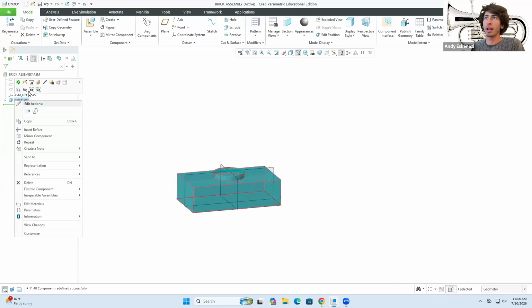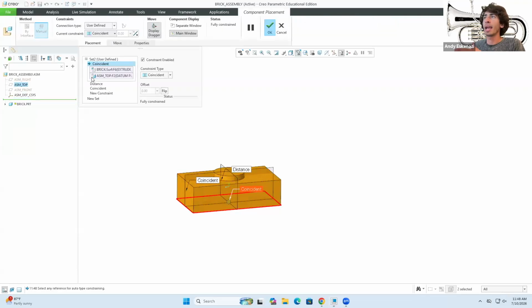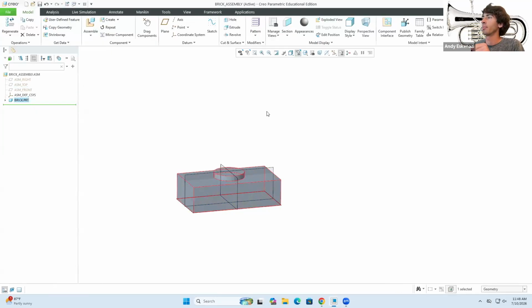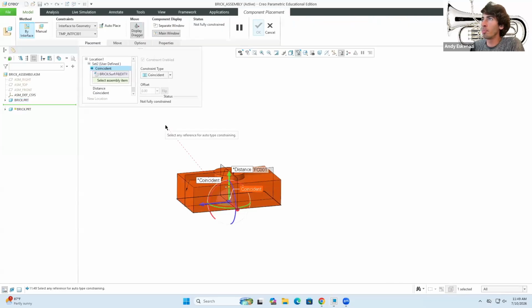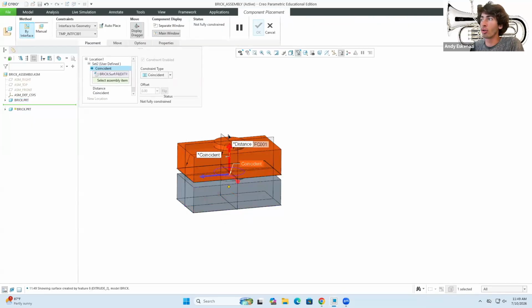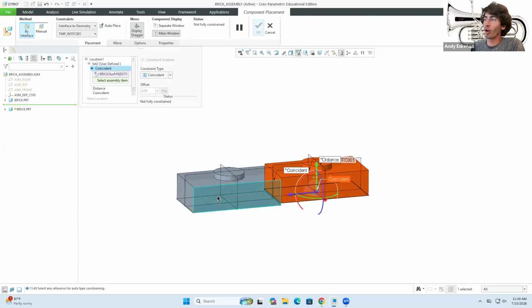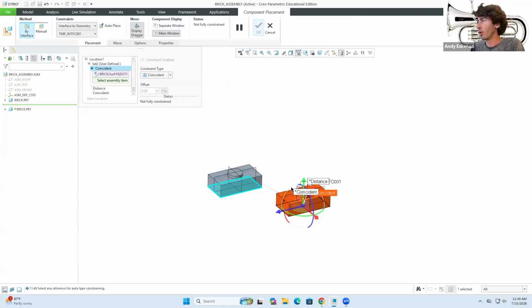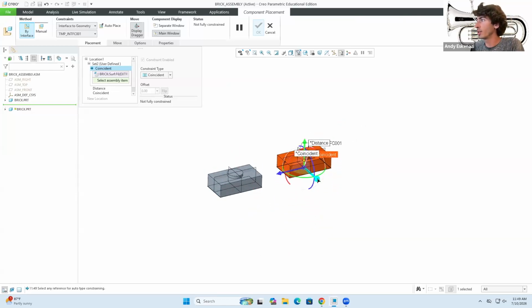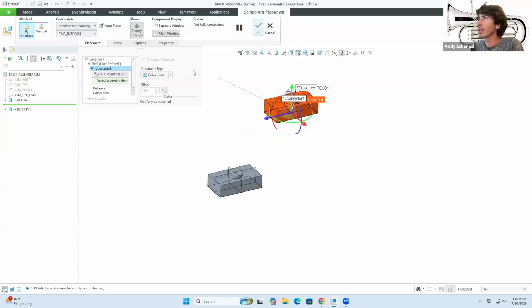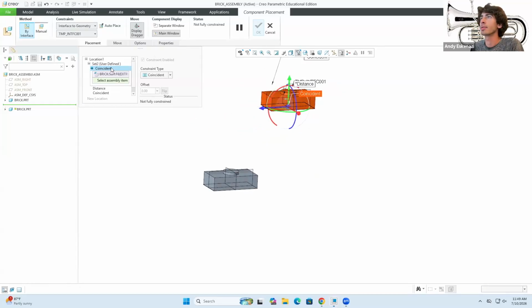Well, if you right click there and you edit definition, again, you can go back to those set of constraints that you've established, you can edit them. Now here to cancel. Let's bring more parts. If you only have a single brick, as the design that we have in here, there's multiple things you could do. One thing is to click here, do Control-C on your keyboard, Control-V, and you will create a new brick. So if I go to the arrow, I can bring a new little brick in here, originating from the one that I just created, right?